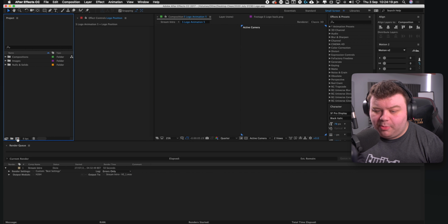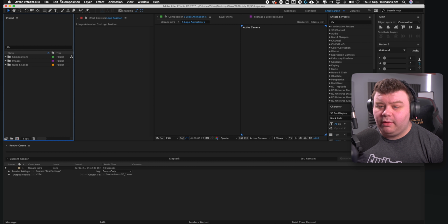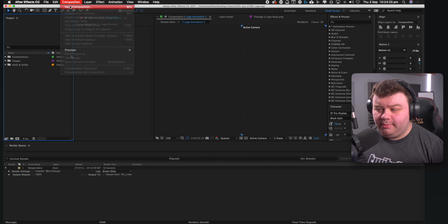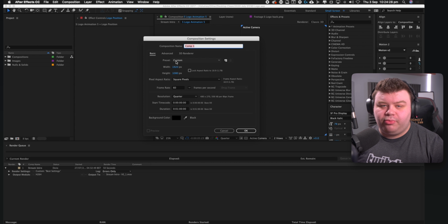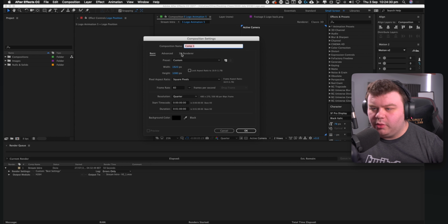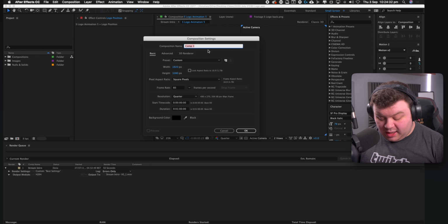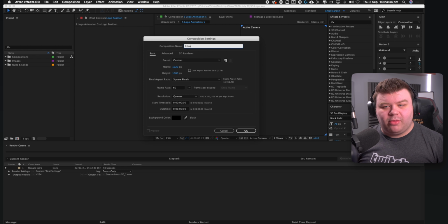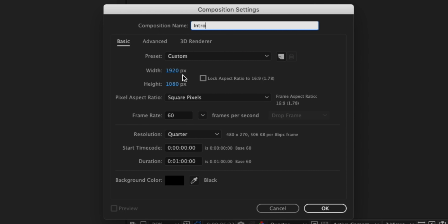I'm going to make a brand new composition inside of After Effects. I'll click on the Create New Composition button right here, or I can go to Composition, New Composition, and it will load up the settings window for your comp. We'll call this one intro, with a width and height of 1920 by 1080, 60 frames per second, and I set my duration to about 1 minute.